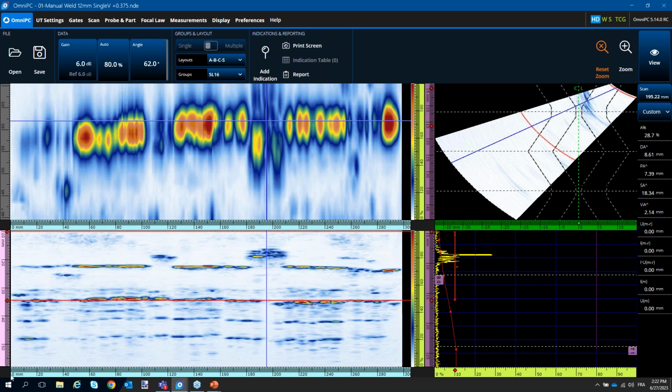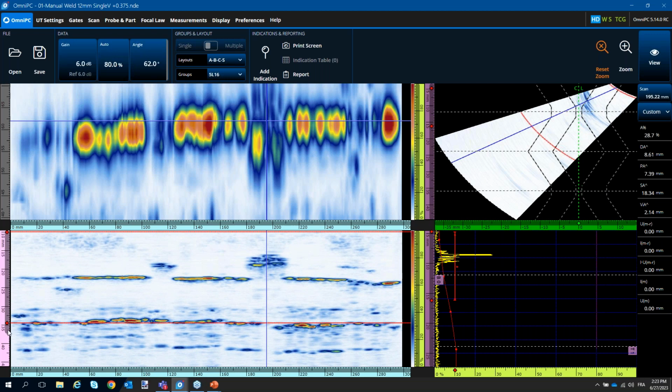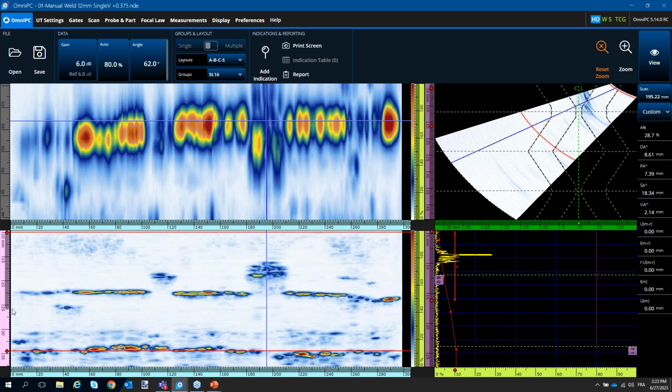You may remember earlier in the meeting, I said the closer the signals are in time, the more useful the merge B-scan is, and the farther away they are in the material and skipping over, the less useful the merge B-scan becomes anyway. So most of the interesting signals will still be early in the material.